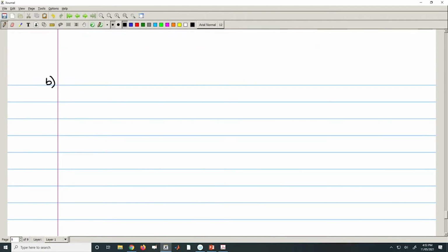Now, the second part, again we need to find beta. So, beta we know is given by omega root mu epsilon times root of 1 minus Fc upon f square. Okay, so first we need to find Fc.